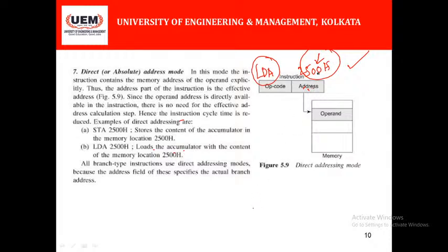It is a memory address. We go to memory address 2500. What is the data here? Say 07H is the data here. What we do is load this data, because LD stands for load, A for accumulator. We load or transfer this data to the accumulator.